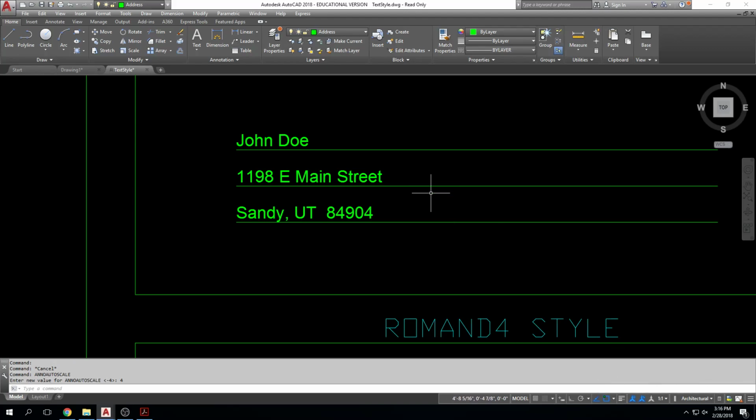It's one of those nice things that if you turn it on and you're just using a normal workflow, it kind of just saves you. It helps you through the whole process by adding the annotation scale to everything. It doesn't help if you're trying to very rigidly control how your annotation looks, because it just adds scales to everything. But it is good when you're beginning, and you're thinking, I'm going to forget to change the scale, and my text won't show up when it needs to. It's a good thing to have turned on, okay?